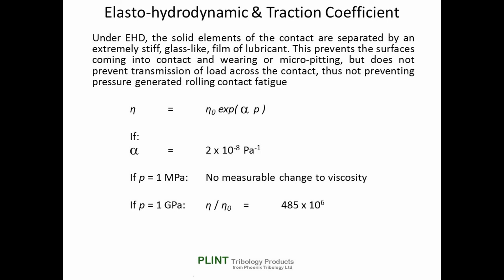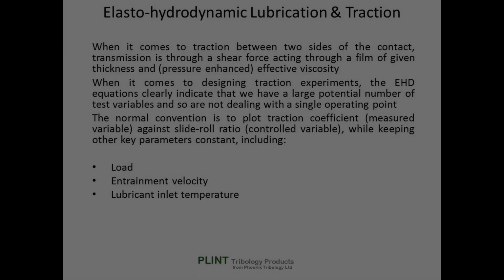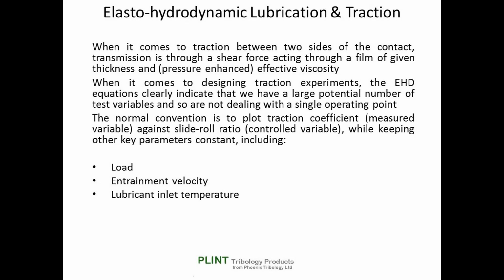When it comes to traction between the two sides of the contact, we are clearly dealing with transmission of a shear force through a film of given thickness and pressure-enhanced effective viscosity. When it comes to designing traction experiments, the EHD equations clearly indicate that we have a large potential number of test variables. We are not dealing with a single operating point.